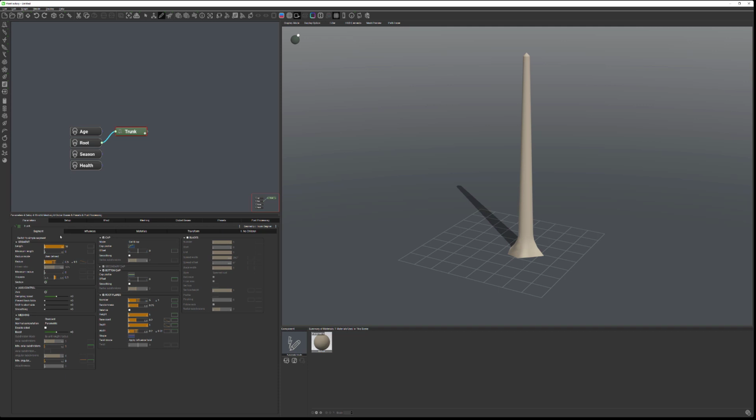So let's go first on the segment where we have a straightforward link. You notice it's 10, we can switch to 5. An important thing to pay attention to: this is a unit, so we're going in meters or whatever you set your units to. But most important for us is the next window. The reason is, you notice it has a plus and minus. This provides variations. So if I put in 2, it means it can be anywhere from 3 to 7.